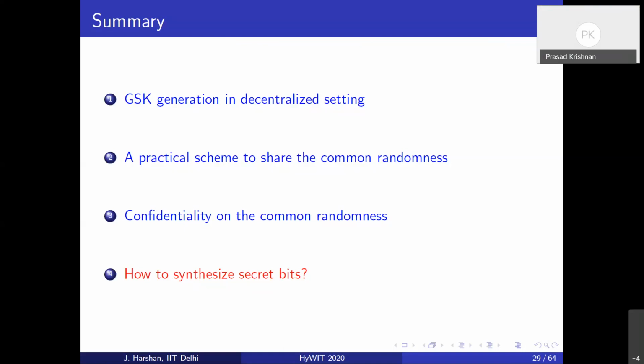Yeah, so that's an interesting question. What has been shown is, especially when key exchange methods are implemented on resource-constrained devices, executing a Diffie-Hellman algorithm is going to be computationally expensive. And while there are no issues like quantization and other things, even in Diffie-Hellman they would need to work on an underlying finite field, because the exponent and the base come from an underlying field. The process of exponent computation itself is multiplication several times over a corresponding field with the underlying polynomial. So implementing that is going to be extremely challenging on a resource constrained device.